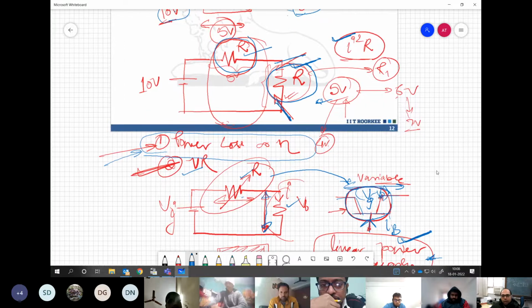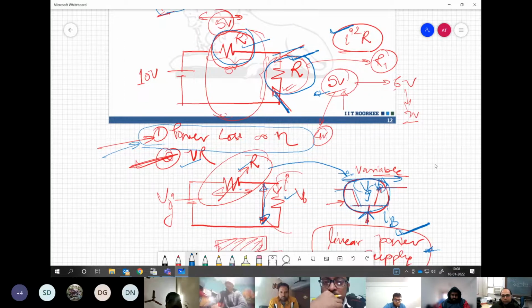Now in the case of DC-DC voltage, let's say the input is DC voltage of 10 volts and the load needs 5 volts of DC voltage. We see that even a resistance could do that job. An equal amount of resistance can be inserted in between, and this can drop the rest of the 5 volts, and then this could be fine. But the problem comes with voltage regulation and the efficiency.